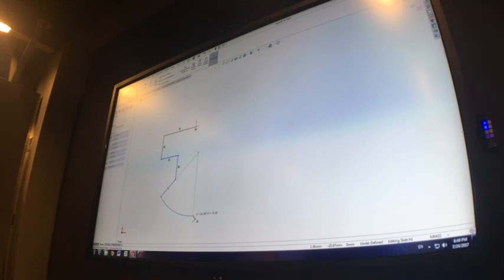See how we get these two guidelines? What this means when we drop our next point here, is it's going to add a coincident relation from the center point of the circle to that angled line. All right, and that's what you can see in the guidelines. I actually don't want that. I will delete it later. But just so you know, that's what's happening here when you can see that sort of thing.